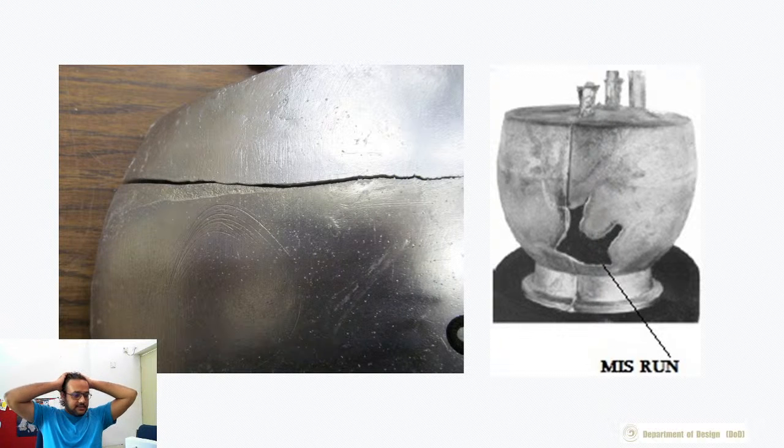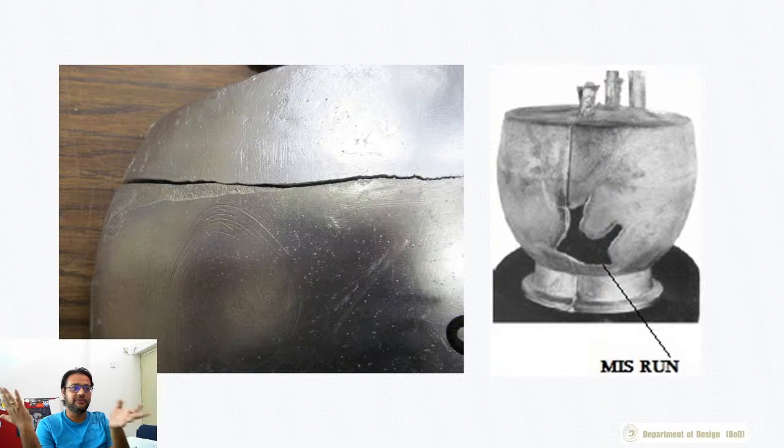Is it a slow process for making things in large numbers? Let's put it that way: sand casting is slower than die casting. Die casting is fairly fast, and die casting is slower than injection molding. So if our gold standard for fast production is injection molding, then it is fairly slow, but it is still